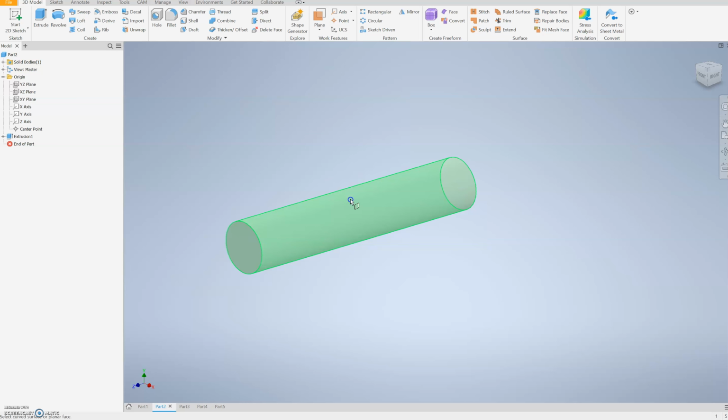and parallel to plane. So I click on that one, and at the bottom here, it's going to ask me to select my curved surface. So there's my curved surface. And now I want it parallel to a plane. So I'm going to use those origin planes. If I come back and expand my origin in my browser, I can select where I would like this to be.